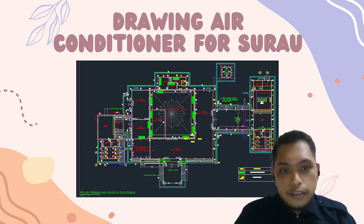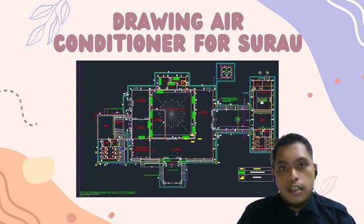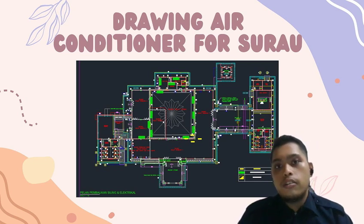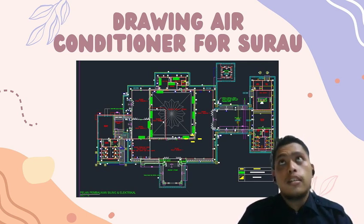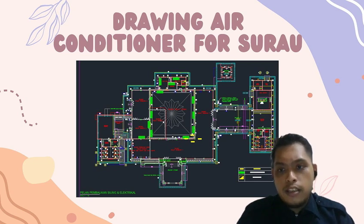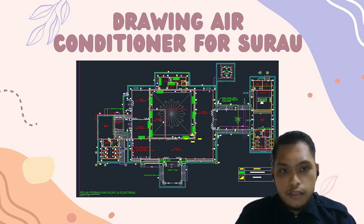Same goes for the air conditioner, where you need to perform a calculation to know how much horsepower is needed for each area. If it is a small area, we use the total area in feet times 16 divided by 9,000, and for the big area we calculate that area in feet times 70 divided by 9,000.